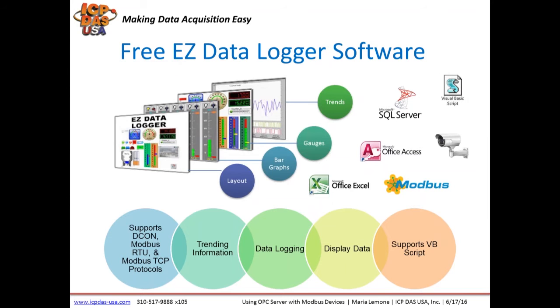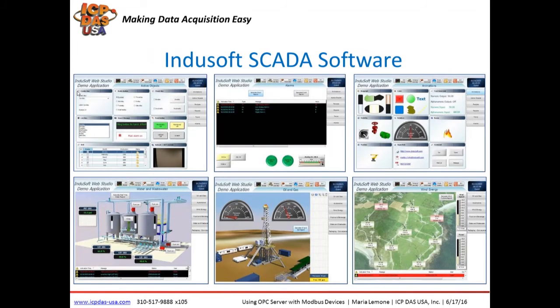SoftGraph runs on our Windows PACs that can run with WinGraph, which I just showed you, and it allows you to set up an easy-to-use HMI. You can make up to 200 different pages in your HMI. It supports password security, animated graphics, alphanumeric text. You can use bars to show tank levels and pressure information. You can also use gauges and trend graphs. This is free software that we provide with our IEC 61131 programmable controllers like the WinGraph and SoftGraph controllers.